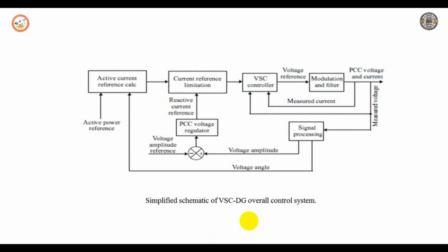This also limits the reactive power transfer, which is basically controlled through changing the converter voltage amplitude. The first limitation is discussed, while the second limitation is elaborated further. Since the control of active and reactive power can be performed independently, the active and reactive current can also be treated independently. A simple schematic diagram of the overall voltage source converter is shown in the figure.